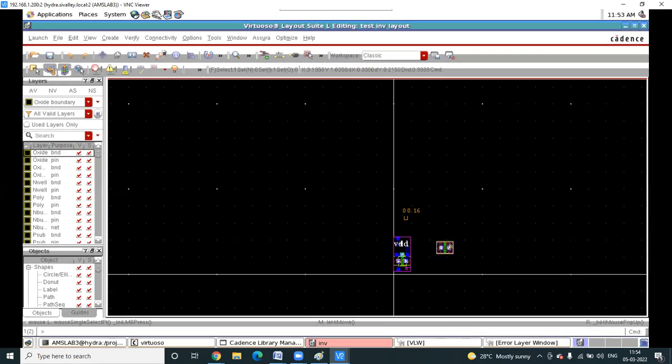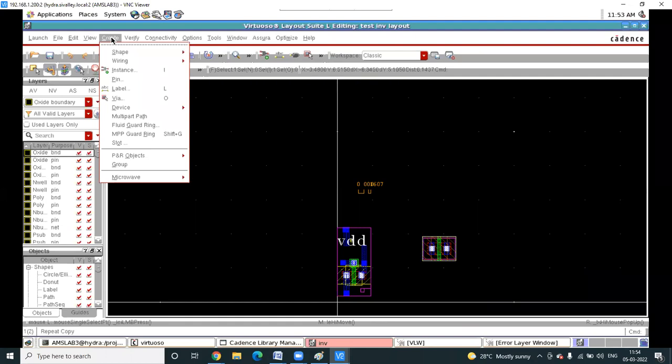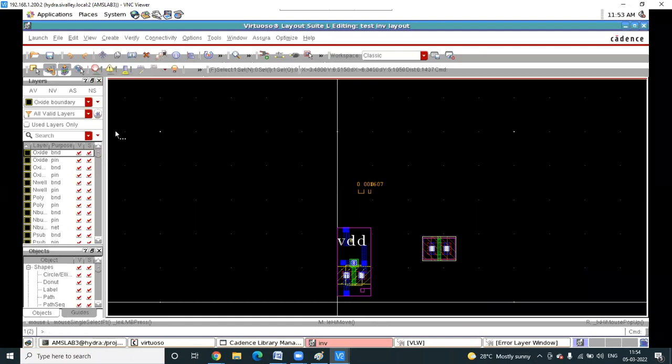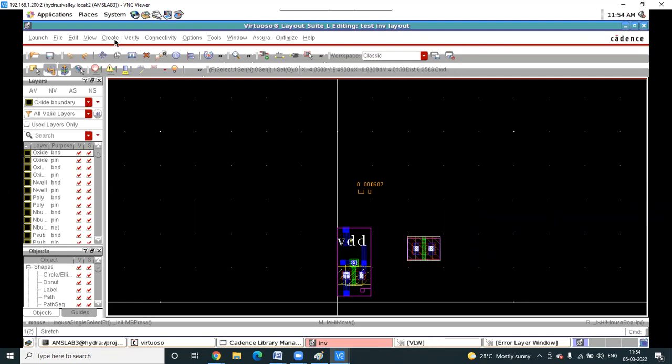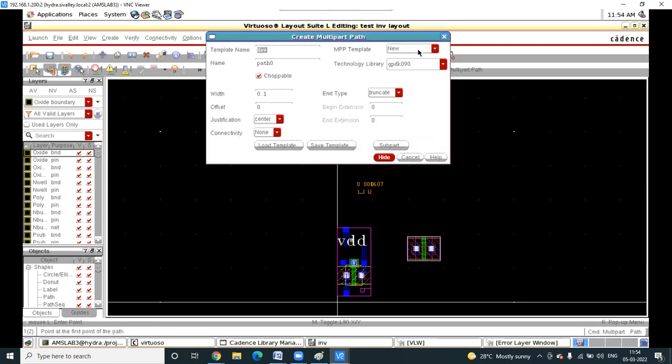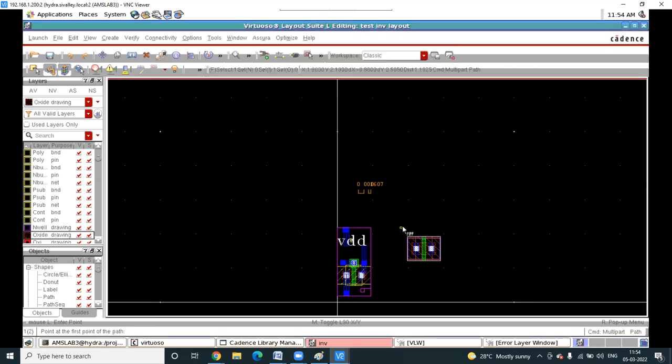This is a PMOS, and you need to add an N tap. N tap has to be drawn.